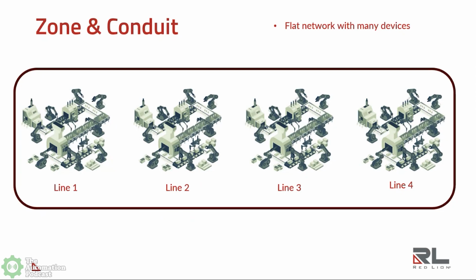In this customer situation, he allowed a third-party contractor to come in and plug into just a gray port that was there at line one. That laptop was able to access every other industrial device on the plant floor, find all of his Windows-based HMIs, and then target them and infect them, all without the third-party contractor knowing that this happened. They only knew it happened when the production line stopped.